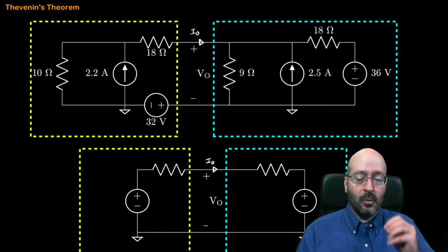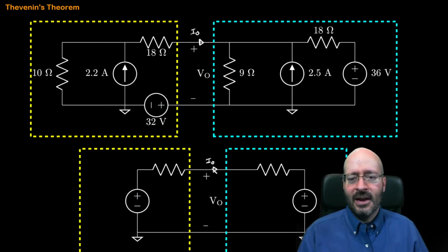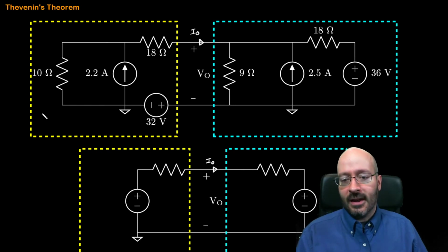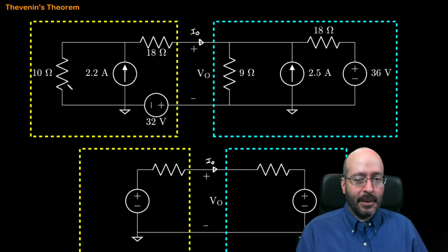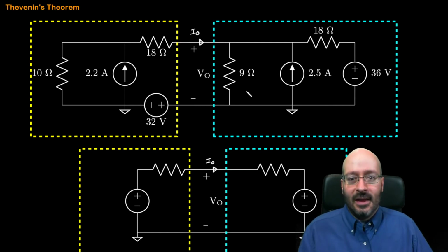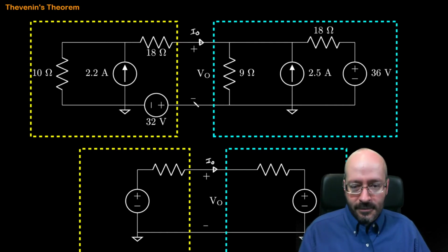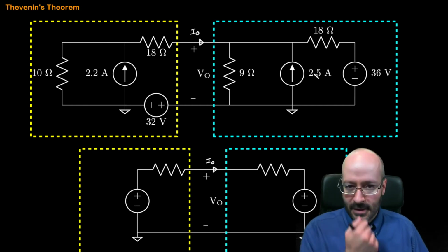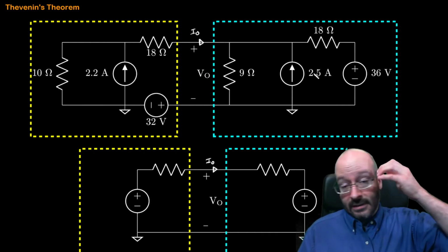And there's the circuit. We're going to break it into two subcircuits. Completely made up, by the way. But maybe you think of that as the microcontroller, and then this is the circuit that you build to connect to that microcontroller. Well, what's the voltage here? So what's the microcontroller going to read? And then how much current is required to drive your circuit? You've got to think about that when you're designing.